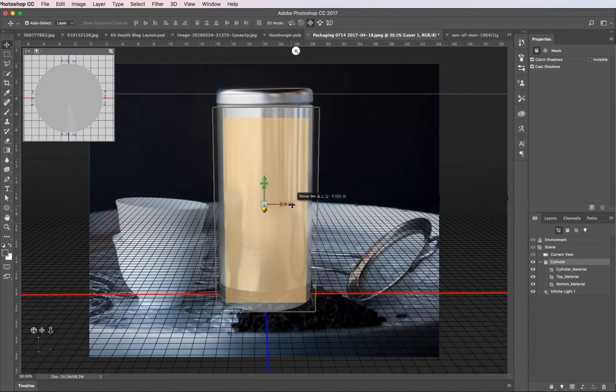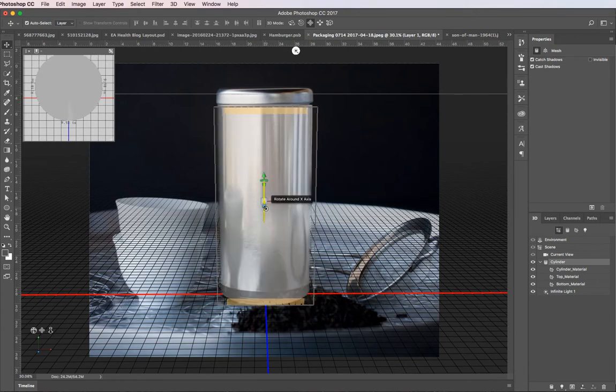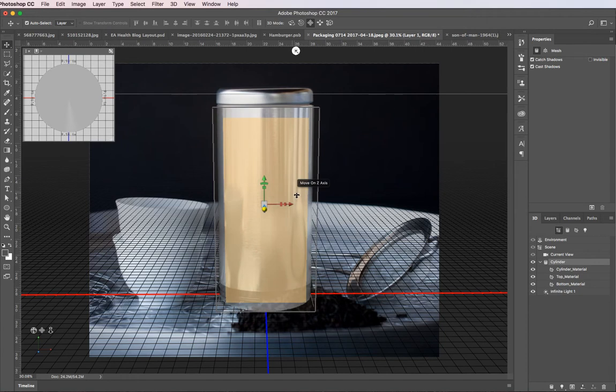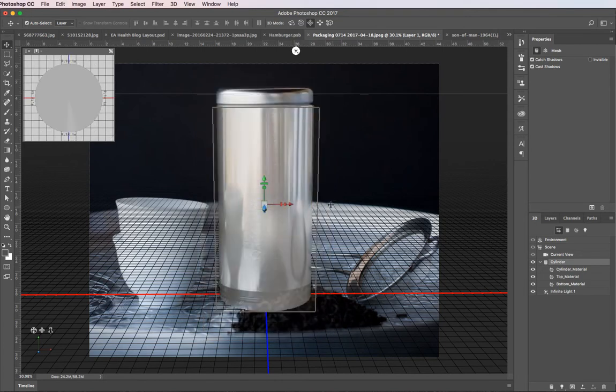And if you hover over the move, you can move it one way or the other. In this case, I actually hovered over the z-axis by accident, so it was moving it in and out of depth. So these kind of do similar things to the move tools, but they allow you to do really controlled movements. And in the middle here, you have a cube, and if you hover over that, oops, there it is, you can scale it uniformly. So that's the fourth thing you can do. And you can do all those from all the different axes.